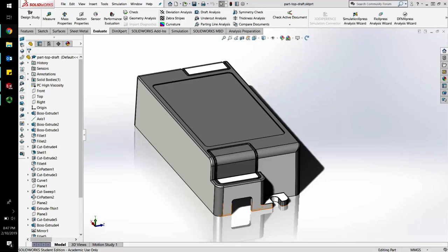Shown in SolidWorks is an AC LED driver. In order to check the manufacturability by means of, perhaps, a pull mold, undercuts should not be present in the direction which the mold will be pulled from, in order to help reduce costs of manufacturing. To determine the presence of an undercut, there is a feature within SolidWorks to check.